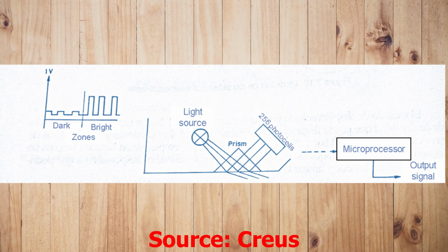In the fixed prism model, the critical angle is determined by the ratio of shaded area to light area of a detector that captures the light reflected through the prism. The optical detector is made up of 255 photocells that send pulse trains. The number of high pulses corresponds to the light area of the image, and therefore defines the position of the shaded edge. A microprocessor compensates for temperature variations, linearizes the signal, and outputs the units of concentration of the fluid.